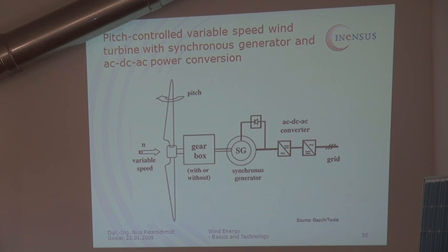Now imagine a very variable wind, gusty wind, or high turbulence. You will lose efficiency if you get to a tip speed ratio of 4 or 7. Therefore, it is important for the efficiency of the turbine to adjust the rotational speed of the turbine very quickly according to the wind speed. And this has to be covered by the control of the generator.